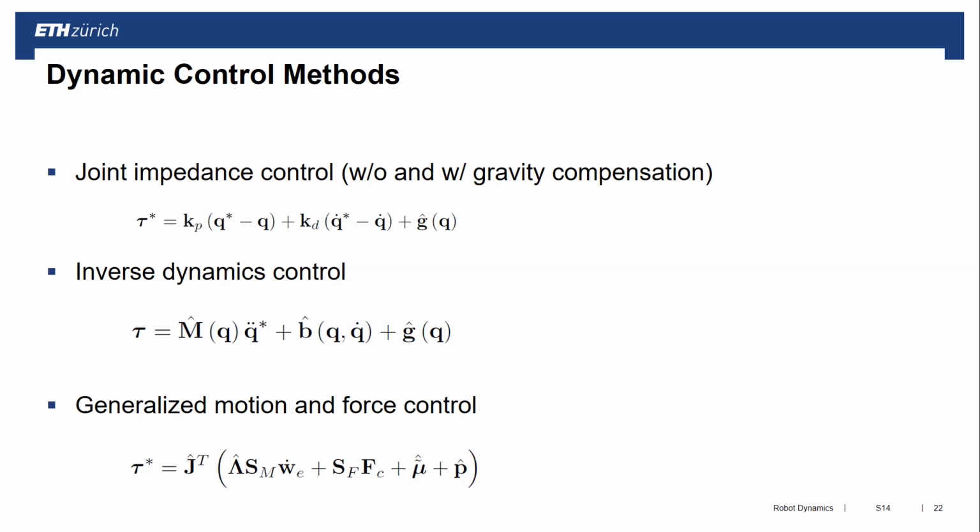So what you want to have is a compensation for this change of inertia. And this is done through inverse dynamics. In inverse dynamics, all this compensation is done by inverse dynamics, and we are making this PD control on acceleration level. So assume we have a perfect model of our system, then what we could write down with this is essentially joint-level PD behavior, where we have just an identity matrix across all the joints. So we can fine tune these PDs and define how the robot should react independent of its current configuration.